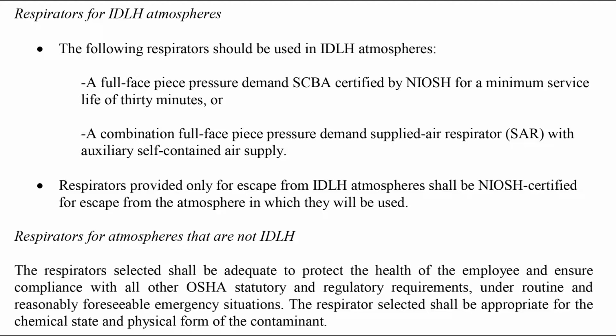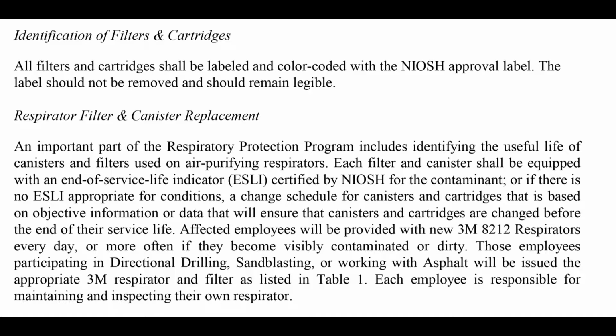The respirator selected shall be adequate to protect the health of the employee and to ensure compliance with all other OSHA statutory and regulatory requirements under routine and reasonably foreseeable emergency situations. The respirator selected shall be appropriate for the chemical state and physical form of the contaminant. Identification of filters and cartridges. All filters and cartridges shall be labeled and color-coded with the appropriate NIOSH label. The label should not be removed and should remain legible.